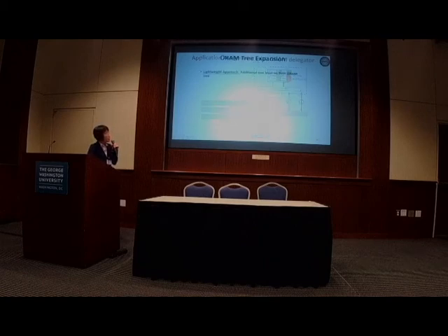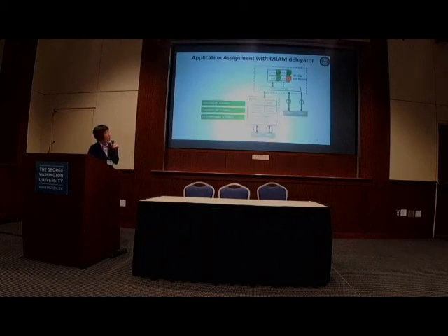But you may still need to run your applications on both this buffer on board control part and the non-secure application. This is the DRAM, the regular DDR interface. In other words, you can run both secure and non-secure applications on this channel and this channel. But you have to think about what happens if your memory capacity increases, which means that your ORAM tree increases, and then you don't have enough of these resources here. You could still leverage the remaining regular DDR interfaces over here.